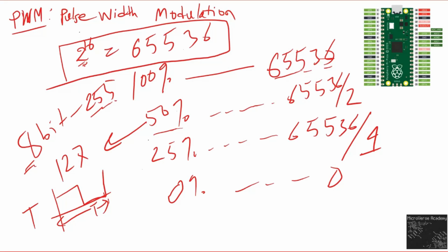Also, in the case of LED brightness controlling, you need to know the max frequency you can go with. If you go with too low a frequency, you will see flickering, or you might have some problem if you cannot handle this frequency correctly. I will show you this effect of frequency in a minute.